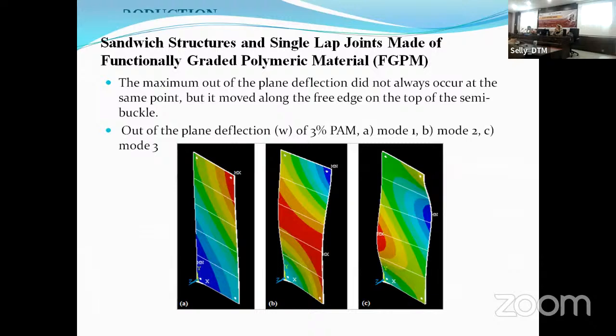Look at that. It's buckling behavior. Yes, it's buckling behavior mode 1. The plate buckles in mode 1, and the plate buckles in mode 2. You can see two buckles. Yes, imagine just on this side. It looks like a beam. And what about mode 3? Yes, you can see mode 3, maximum and minimum von Mises. These are not von Mises, these are deflection points. So yes, I accept it's a buckled plate.